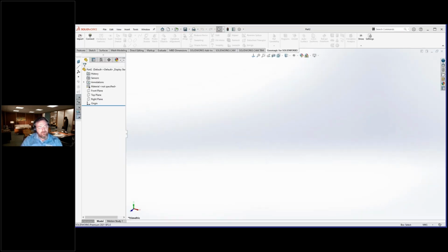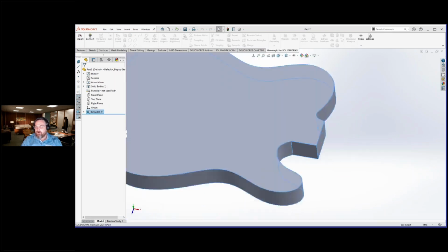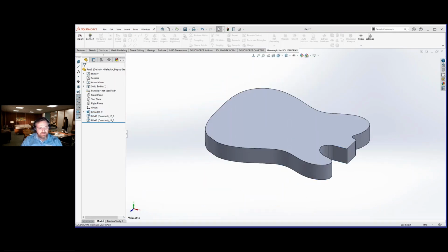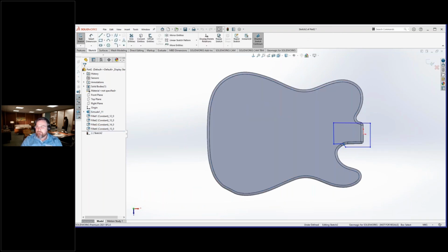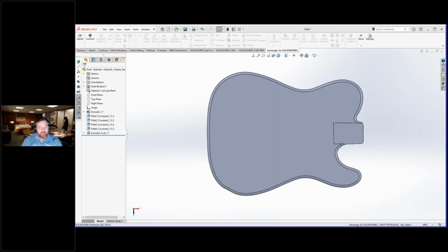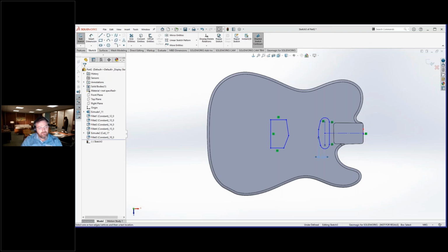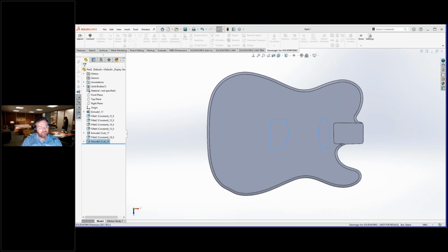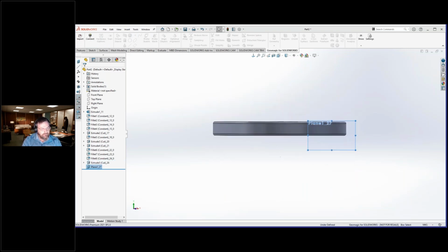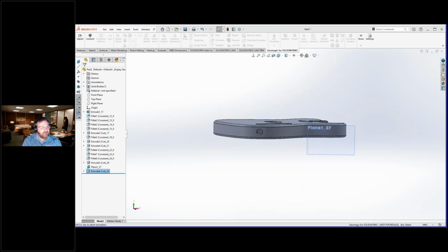So you can see here that I went ahead and cleared out that part and then hit send with the live transfer tool in Design X. And you see what it's doing, it's building it line by line over inside of SolidWorks as native entities. So all of the features, constraints, sketches, relations, all of those things are coming across as native entities inside of SolidWorks.